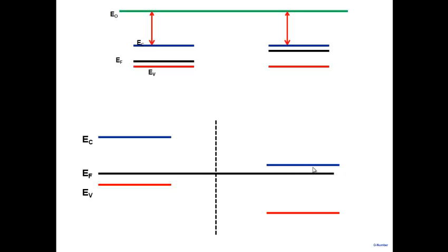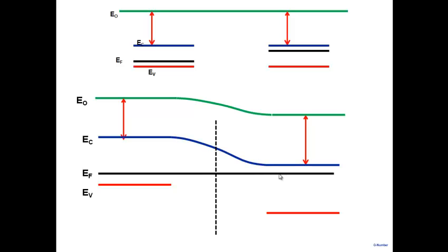And then, once we have these bands EC and all that, we find where E naught is. E naught is away by electron affinity here. E naught is what we said has no vacuum level discontinuity. We connect it in a smooth manner here. And then the conduction band would always be away by electron affinity. Since the materials are the same, it just connects smoothly here and here. All right, so we end up with an energy band diagram of a p-n junction in equilibrium.